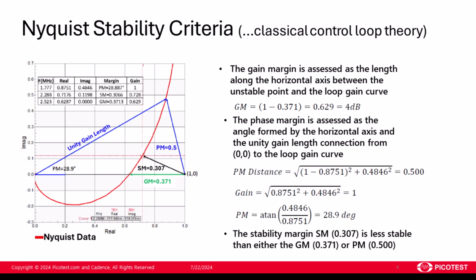NISM is an exact solution for the stability margin, also known as the closest point to the singular instability at 1, 0 on a Nyquist circle. The NISM calculated stability margin is then transformed to the equivalent second-order phase margin as the resulting output. The step-load response, whether the control loop is critically damped, overdamped, or underdamped, is also directly related to the stability margin.